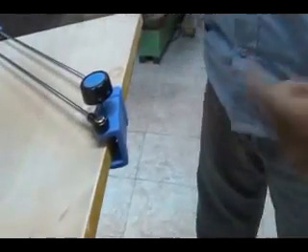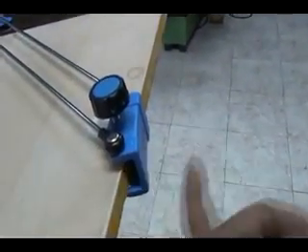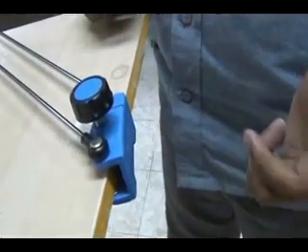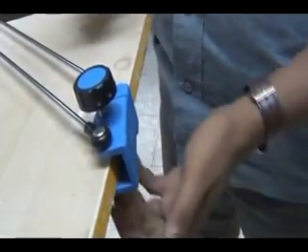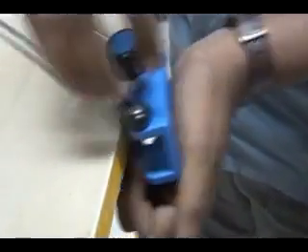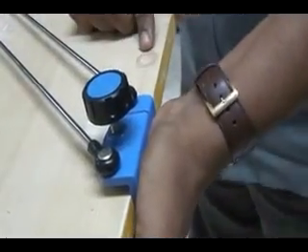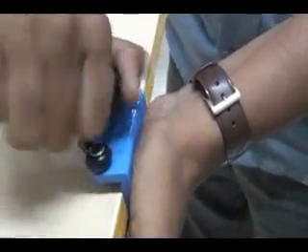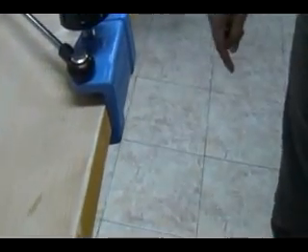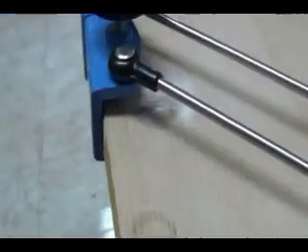You see, this is a wrong one. You should not have any gap. There should not be any gap in the fixing of your drafter. This is very much essential. That gap you should avoid. Carefully fix that flat portion rigidly with the flat portion of your table. If you find a gap between the holder and the table, then you will find error in your drafting usage. Is it clear?